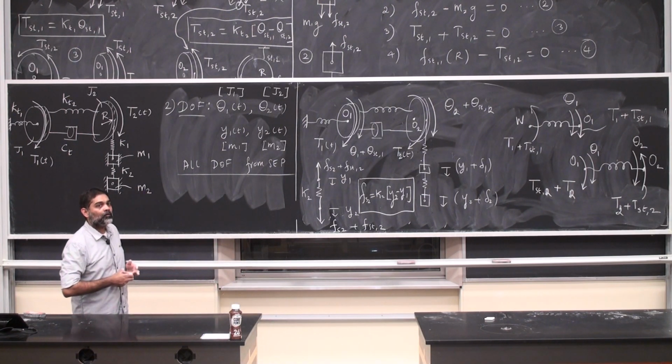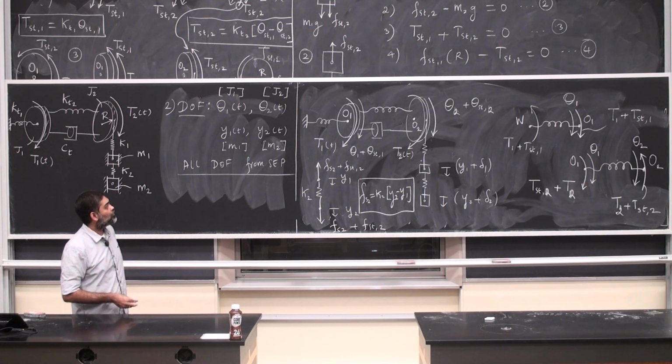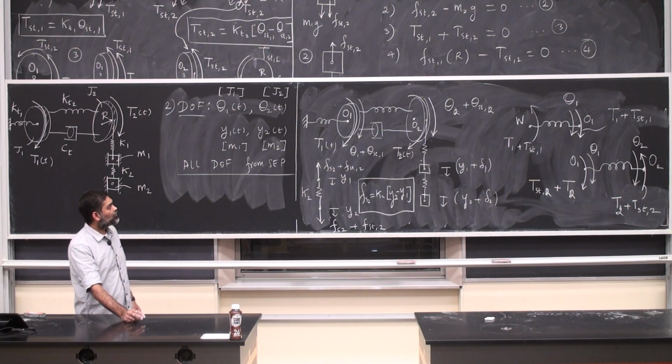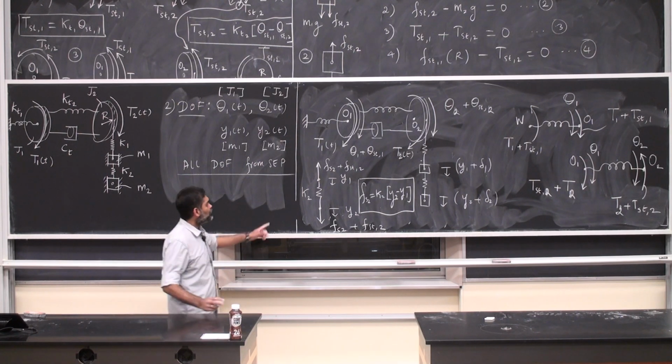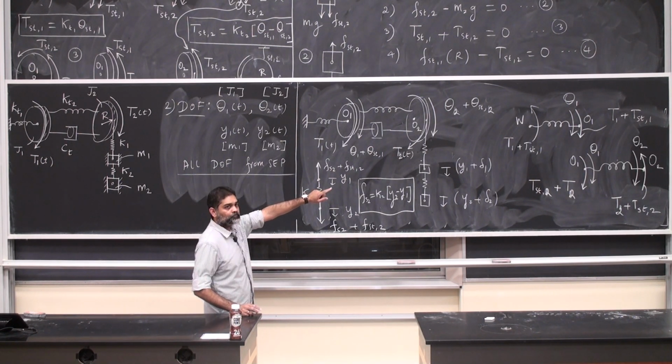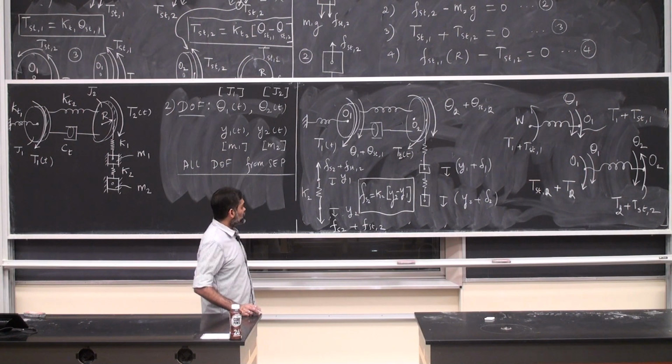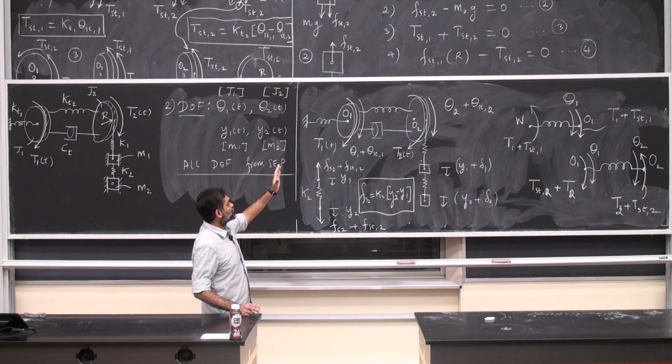And then also, one more question. Is it just safe to assume that whenever a torsional element is applied on either O1 or O2, it flips the sign based off of each particle that it goes through? For example, if it's on the left side of the spring KT1, it'll flip for O1, and then it'll flip again for KT2. Yes, of course, because what you're doing is using Newton's third law.